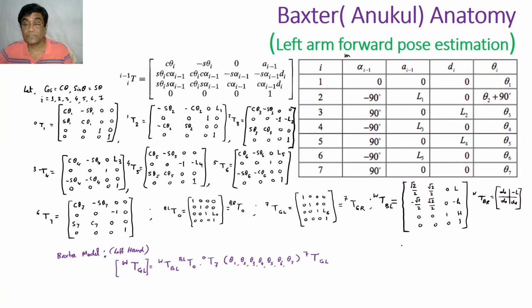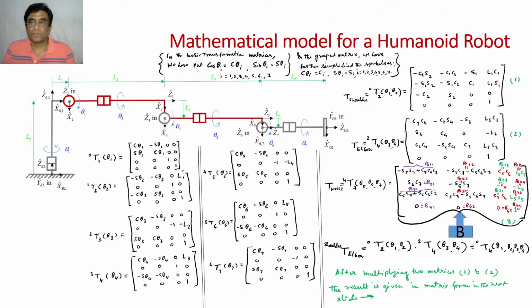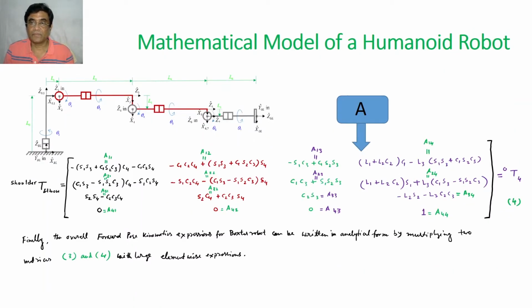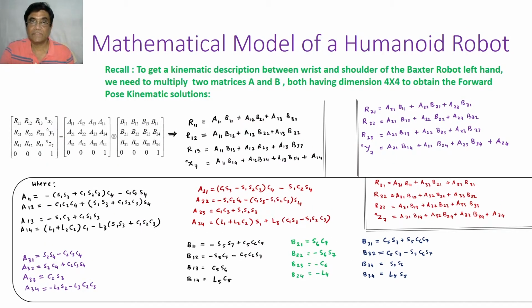So any object in 3D can have 6 degrees of freedom. Now that object which has 6 degrees of freedom, my Baxter robot is trying to capture it using 7 degrees of freedom. So in the joint space it has 7 degrees of freedom, 7 joints are there. Again, in the video it will be clear what those 7 joints are. I have 6 degrees of freedom, so how many functions will you be able to generate? 6. How many unknowns will there be? 7. So that is the redundancy, right?